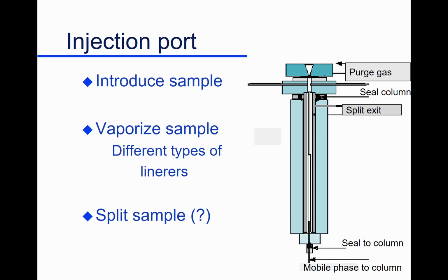The vast majority comes down here. So we put a syringe down here, our needle's about this point. We push it down, we get our sample put in here. This is hot, 200 to 250 degrees centigrade. It goes poof, and then it gets pushed down into our system for analysis. So a very simple system, hot, simply to vaporize the sample.